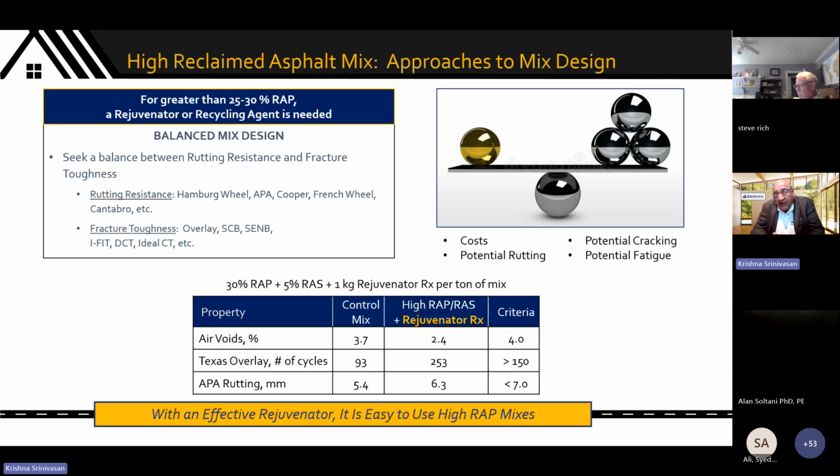The other way to do it is through BMD, or balanced mix design. And this is done at the mix level. In balanced mix design, all you're doing, again, this is a fancy new concept for something that's been around with us for maybe 50 years. In balanced mix design, you're just looking to optimize 2 competing parameters. How soft is my mix versus how hard is my mix?